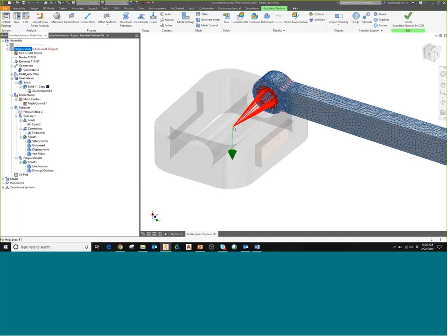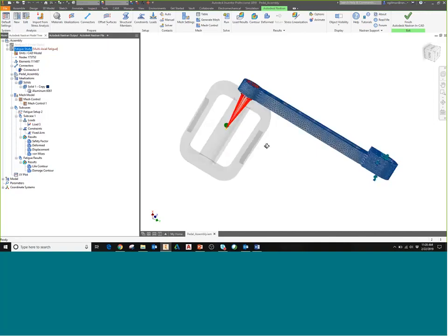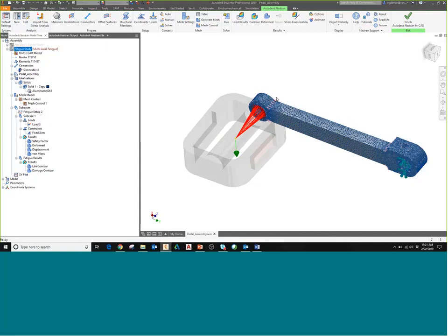So I'm applying my load here. I'm representing it with really just about 100 pound force. So I'm taking basically about half of the load that I would expect from an average size rider to be applying to this. Obviously, some of the load will be taken by the seat of the bike as well as the opposite pedal and some of the other materials involved in that. So I'm expecting about 100 pound force being applied from the center point of the pedal to this other side of my crank arm. I fixed it with rigid body connectors.